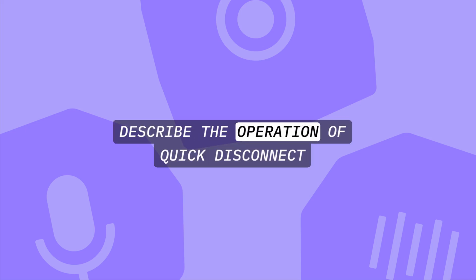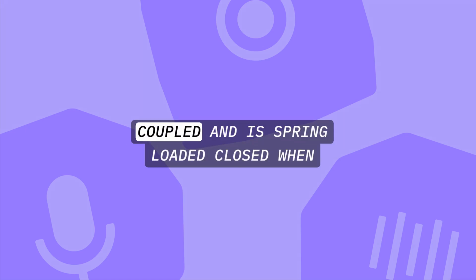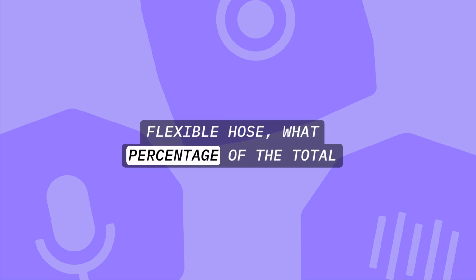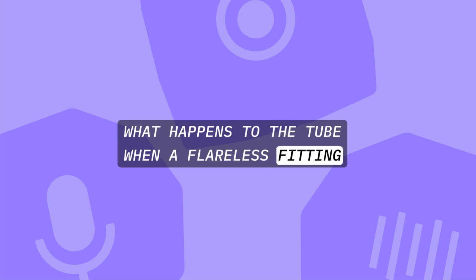Describe the operation of quick disconnect couplings. Each half has a valve that is held open when coupled and is spring-loaded closed when disconnected. If you fabricate a replacement for a flexible hose, what percentage of the total length must be allowed for movement under pressure? Five to 8%.